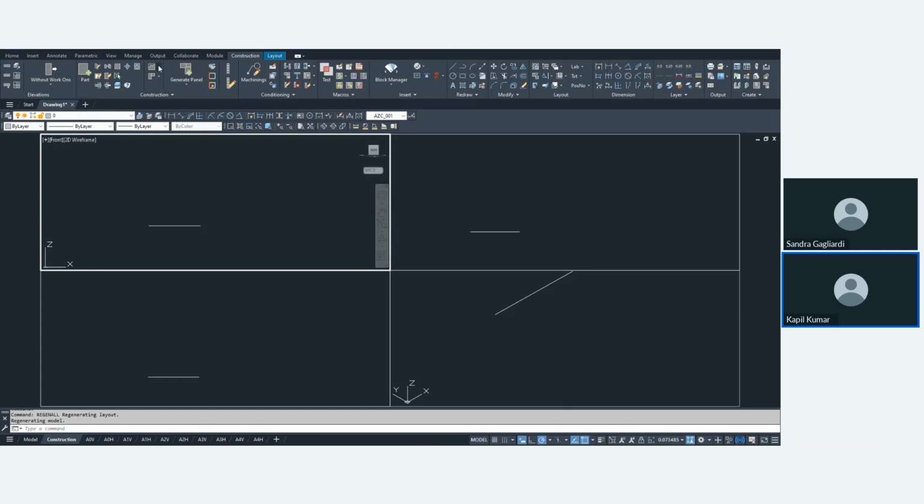Here we have assign outline contour and delete outline contour, meaning if you have already created any part or shape in CAD+T, but you want to change that part into a complex shape or any other shape, and you want all the properties of that material and the name to remain the same, then you simply click here and assign that normal part as your new required part. Likewise, if you want to delete that contour, you can also do it from here.